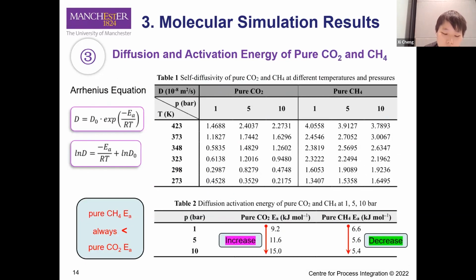And the next is the diffusivity and activation energy of pure gas. At the same pressure, the activation energy of CO2 is greater than that of CH4 because CH4 is lighter than CO2 and it can diffuse more easily. The activation energy of CH4 decreases with increasing pressure, and conversely, the activation energy of CO2 increases with increasing pressure.